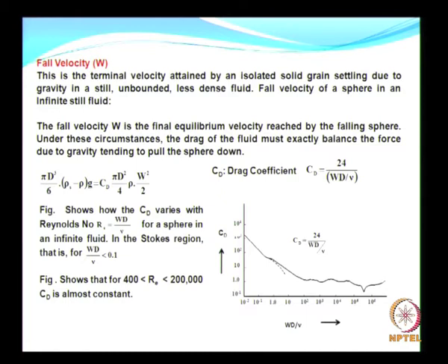So this is nothing but, because it is submerged, you have the density of the sand and the density of the fluid. When you try to equate these two, which is the one that is going to dictate your coefficient of drag, it is also going to control the speed with which the sand is going to move down, which is nothing but your fall velocity.